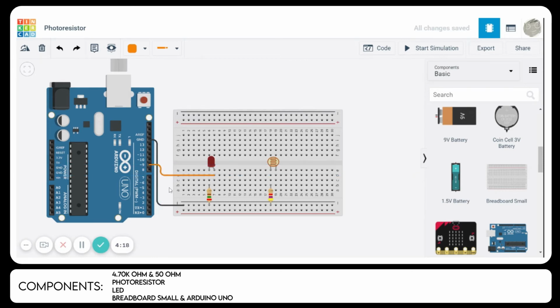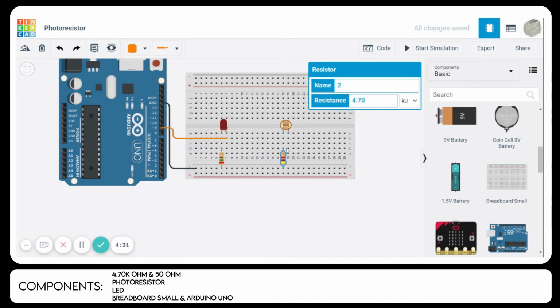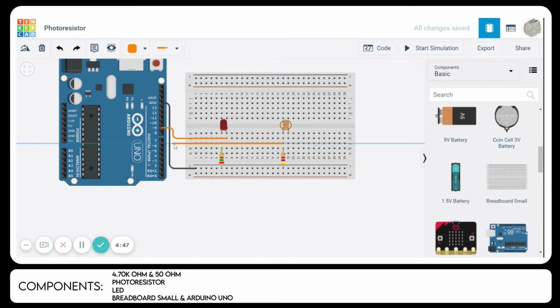Next, since we already added digital port 9, we're going to create a wire coming from our photoresistor group. Right above the resistor with the 4.7, right in between the terminal 1 and terminal 2 pins of the photoresistor and the resistor itself, we're going to create a wire going to A0, so that we can determine that it is also an analog component.